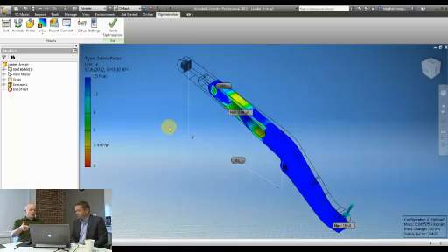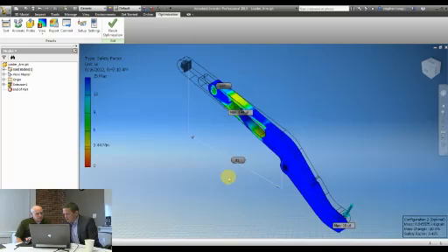So before it breaks, the load on that was something like... Yeah, it was only about 1.5 kilograms because it's for a child's toy. But we've set it, it's 4.5 kilograms, yeah, that's what it's optimized for, 3 times the factor of safety. So if I look at the results, what it's showing us here is that the original model would have failed. The model that we've optimized for, the optimal one, is actually 3.4 times the factor of safety.